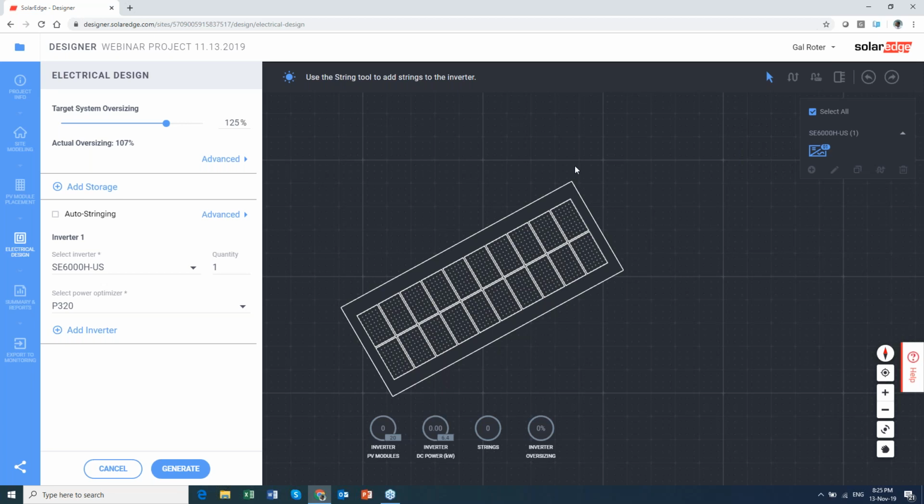As Tyler mentioned in his introduction, we at SolarEdge have our own design tool called the SolarEdge Designer, where you can also start from an address, location of the system, draw the roof, place the solar panels, and then do the electrical design with the SolarEdge inverters and power optimizers. However, we don't have all the detailed mounting. So if you are using the Everest products, or you're using the base tool, this is a very cool way to draw the roof and create the PV layout in the base tool. And then by using this export function, you don't need to recreate this project on our design tool.